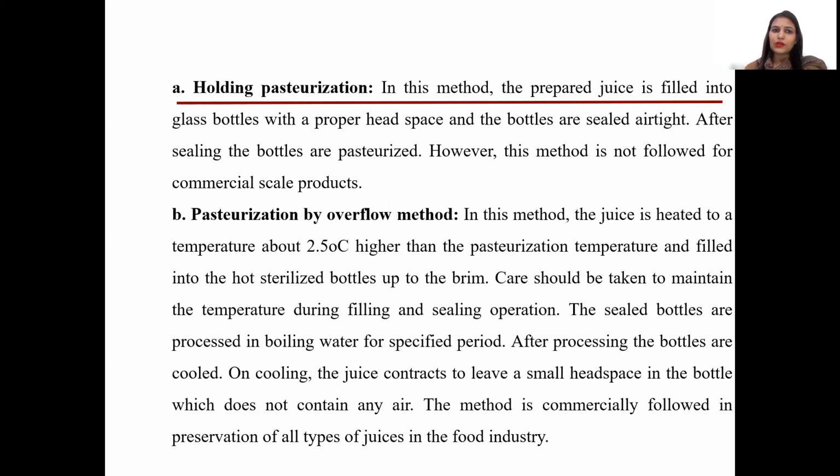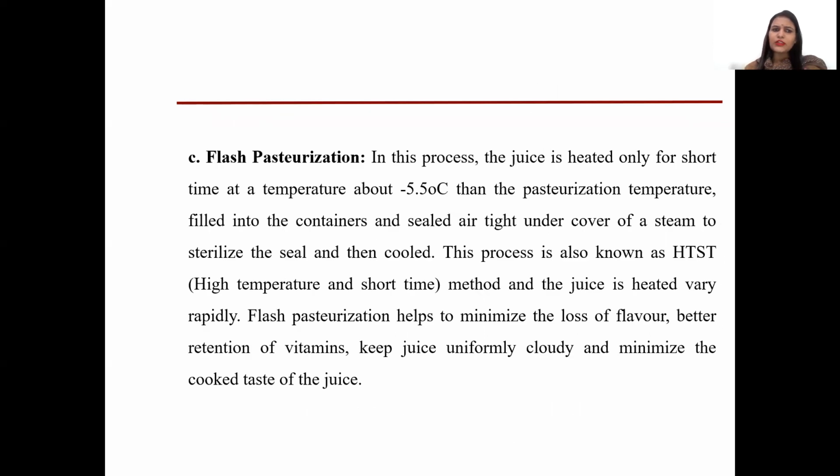In pasteurization also, there are different methods, like the holding method and the overflow method. In the holding method, we have to hold the juices for some time. Overflow means a continuous method we can use at a particular temperature and time combination. So these are the two different methods for pasteurization. There is also flash pasteurization, where the temperature should be above that of HTST and LTLT, about 5 degrees centigrade higher.